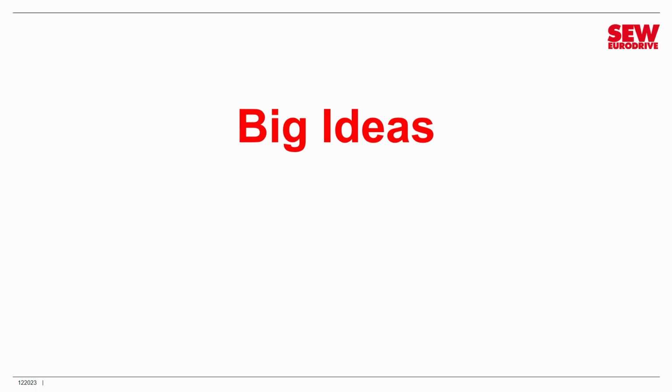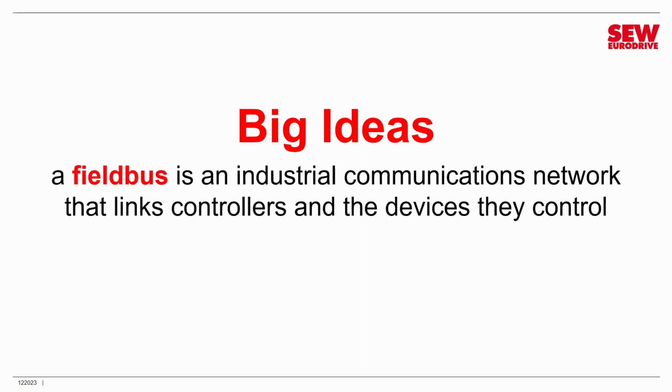First of all, several crucial big ideas. Let's define field bus if this is a new term to you. I've mentioned it a number of times already, but let's get formal about this. A field bus is an industrial communications network that links controllers and the devices they control. Controllers often include things like PLCs or similar devices. The devices they control are enormous, but in our case we're going to be focusing on VFDs.